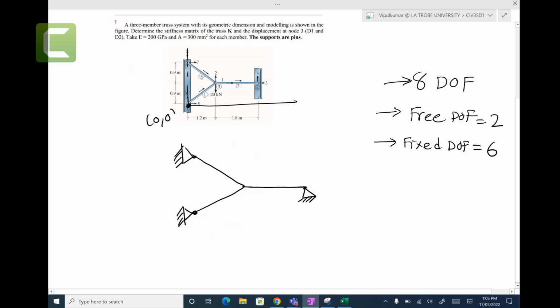That is the origin of the axis, because we need to define the coordinate 0, 0, the starting point of your whole truss system. Why do I define left and bottom? Because then I have the whole system in positive coordinates. Here I will have positive, positive, positive, and it's very easy for me to work with all positive coordinates.